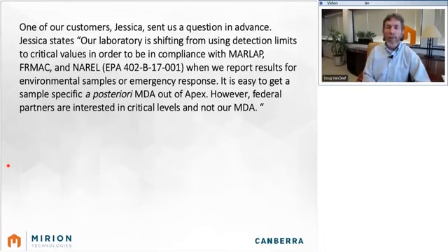Obviously, when you set up a brand new system, all of the calibrations have to be done initially. After that, if you have some kind of a consistent, ongoing quality control and quality assurance process whereby you are checking parameters to ensure that your energy is not changing or the channel number of the peak locations is not changing, that the resolution is not changing, and that the efficiency is not changing, which are common parameters measured in daily or weekly or other frequency quality control checks, as long as your quality control checks show that your detector is stable, I do not think there is any need to go back and do a calibration